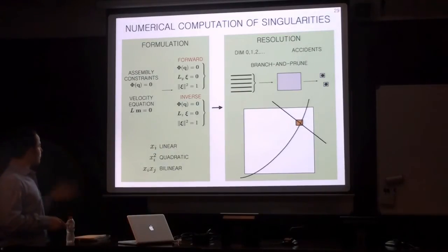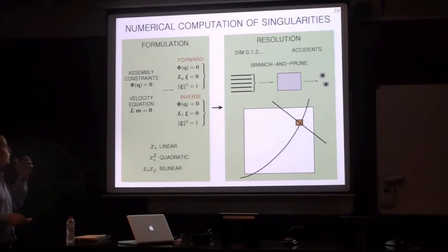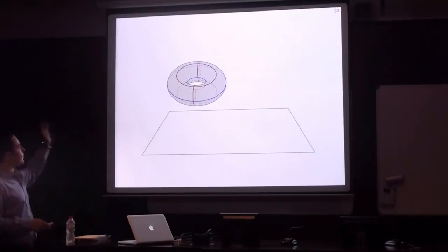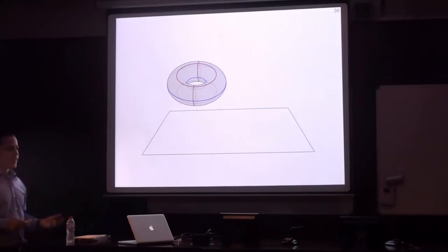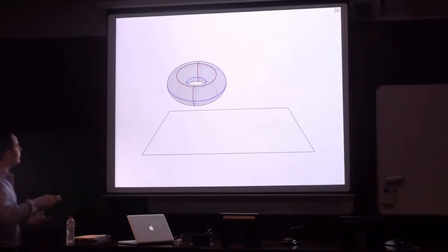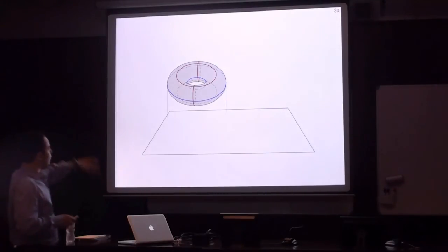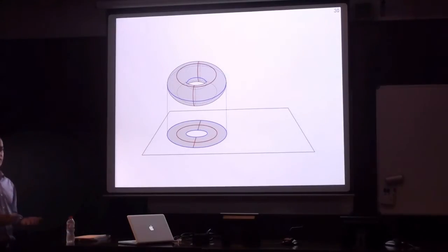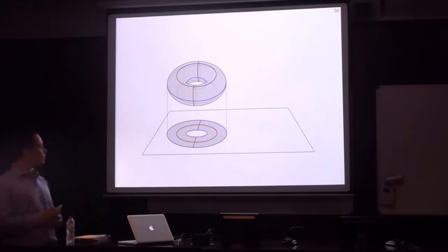So with this method, if we have a manipulator with a configuration space like this, we are able to compute the forward and the inverse singularity sets. But something that is not trivial is how to represent them, because they are usually defined in a higher dimensional space. So the use of projections to the input or output spaces is necessary. However, these projections already provide us a lot of information about the motion capabilities of the manipulator.